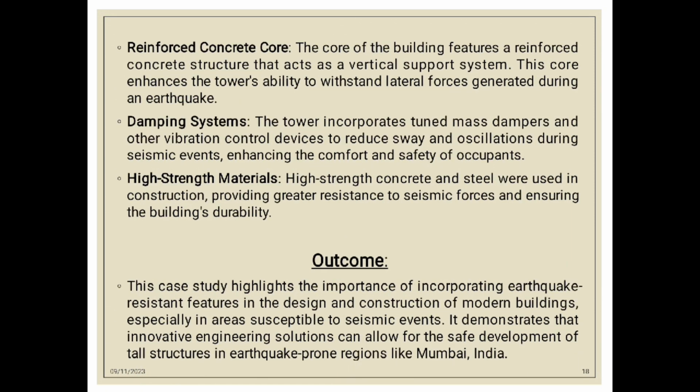Reinforced concrete core. The core of the building features a reinforced concrete structure that acts as a vertical support system. This core enhances the tower's ability to withstand lateral forces generated during an earthquake. Damping systems. The tower incorporates tuned mass dampers and other vibration control devices to reduce sway and oscillations during seismic events, enhancing the comfort and safety of occupants.